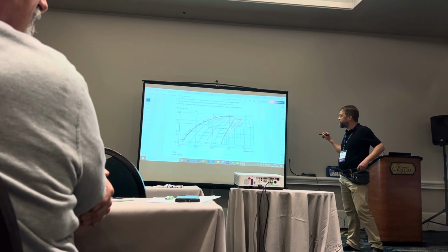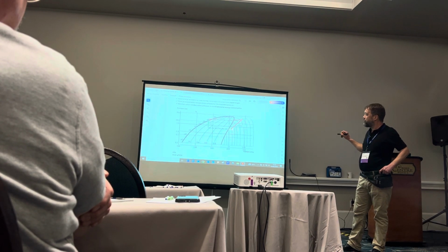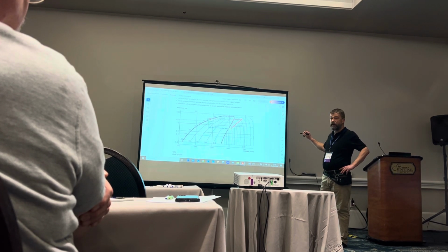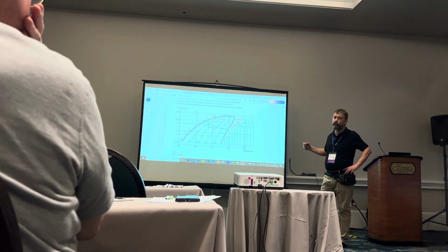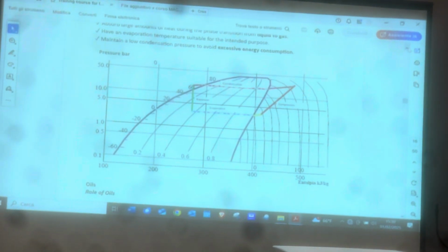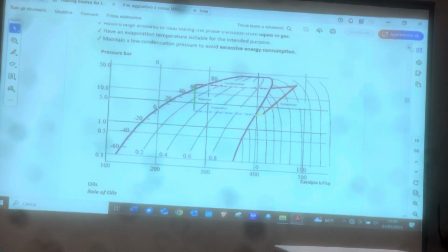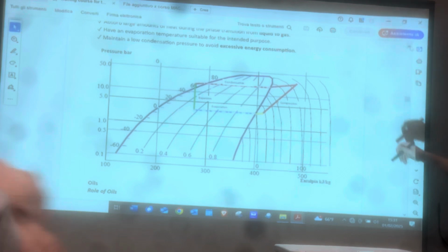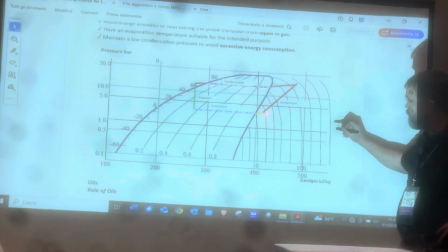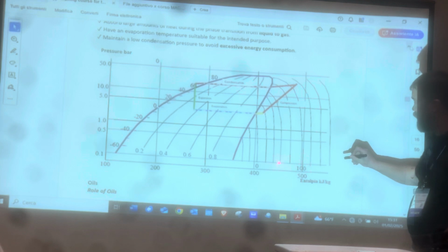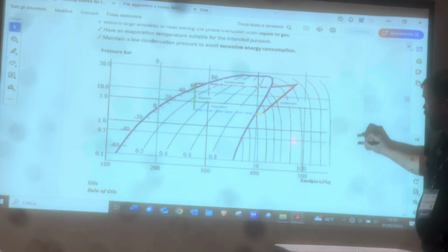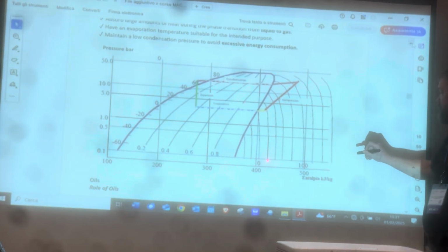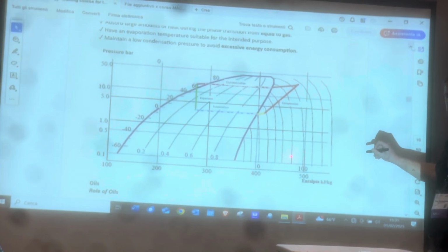So if I start looking at the components, you can see this is your compressor line. Yeah? Again, I told you the compressor purpose is to compress refrigerant, to add energy, and with the energy increase the pressure and consequently the temperature, because we need higher temperature. So the work of energy between there and there is going to be about 8, from here to here is going to be, let's say, about 60 kilojoule of energy in the compressor. Yeah? So I'm